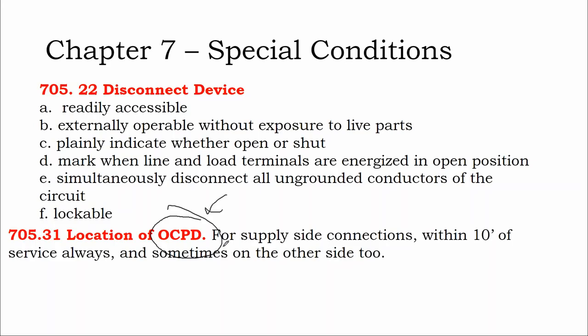That overcurrent could be a breaker. It could also be a fused disconnect switch. Sometimes you can save yourself a bunch of money if it's just one solar array being tapped into the grid, to not put a service panel there, but instead just you're already buying a disconnect switch. Using a fused disconnect switch counts as your overcurrent protection.